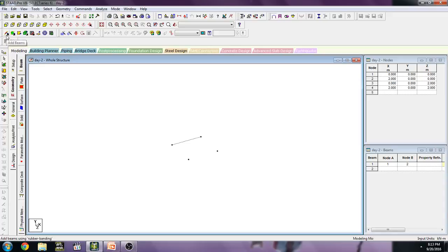First of all we have to create the beams. If you want to create a plate, then just simply add them, and these are the 4. Choose the beam cursor, then you can see these are common beams. 4 beams are created over here because of 4 nodes. Then if you want to make a plate over here, then just select this second option. Here is written the 4 noded plate. Select it. Second, third, fourth. This is how one plate is created.